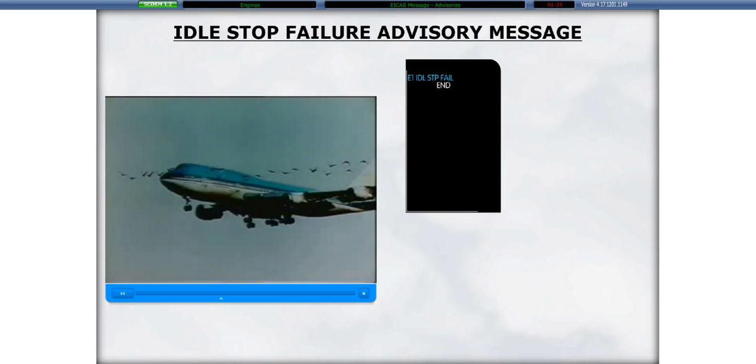Most bird strikes occur close to the ground, at the very time when there is least opportunity to appraise the situation. Nevertheless, the record shows that establishing flight path control first before taking action on the engine is a more successful strategy than taking immediate action with the engine. There have been accidents resulting from bird strike-related rejected takeoffs above V1 speed, and in each case, the airplane was in fact safe to fly. Therefore, rejecting a takeoff due to a bird strike at speeds above V1 is not considered to be appropriate.